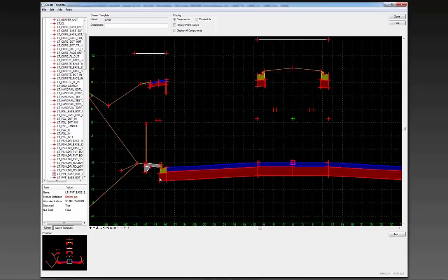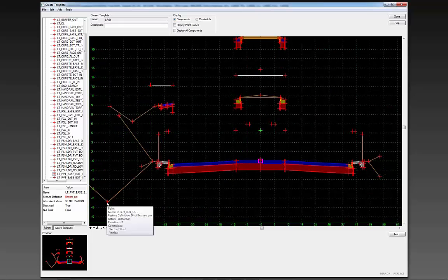The one reason why we did put them all as bottom PM is if someone ever wanted a subgrade surface, basically just showing where the top of subgrade was, we could display all the bottom PM points, create a terrain surface from that, and provide them with that surface.